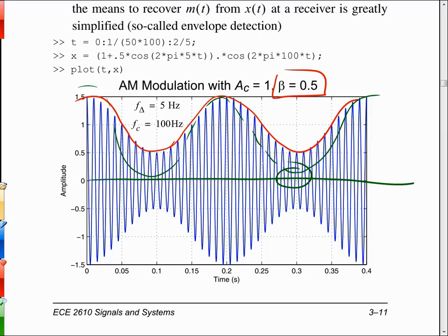And that means we can use a simple detector known as an envelope detector. When you study electronics later on, you're going to find that if you were to process this waveform through a diode circuit, a resistor, and then a capacitor, the diode rectifies the signal, so it throws away all the negative half of the waveform, anything at negative voltage values. And then combined with the capacitor, it is going to stay charged up in between these individual cycles so that what will come out,